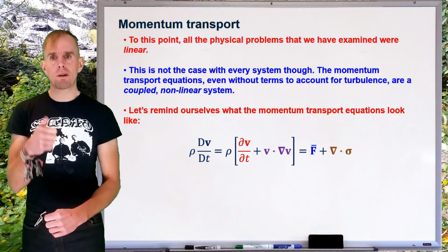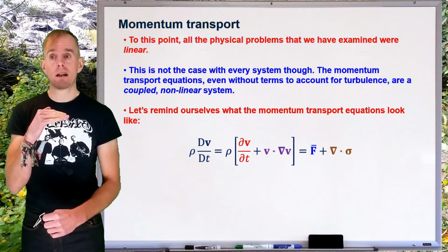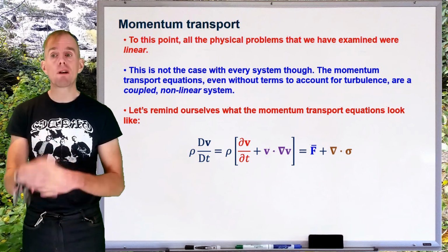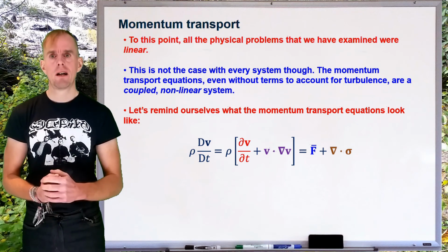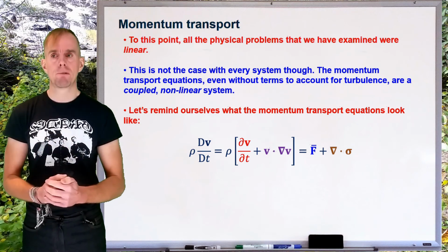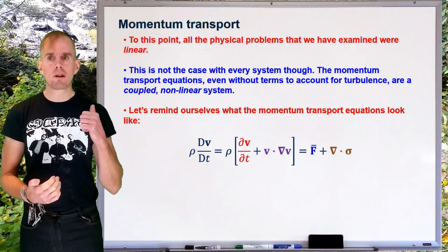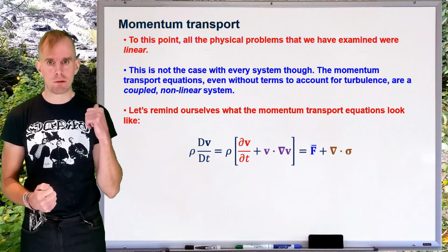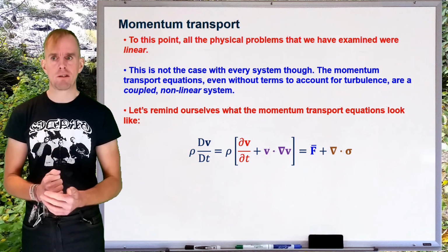And so we've got mv, momentum, but divided by a volume. So it's volumetric momentum. Now of course there's another subtlety here, because we've got time. We've got partial dv by partial dt times rho. And so what this actually describes, strictly speaking, is the rate of change of volumetric momentum.